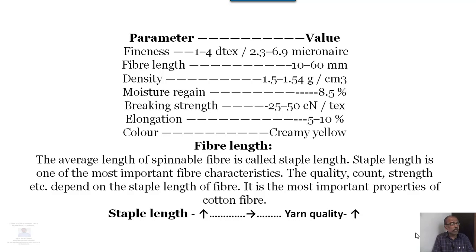Now, as the staple length is more, what is the consequence? Actually, the more the staple length, the better the yarn quality. Excellent yarn quality is going to be obtained, because when long fibers are there, these yarns can have an evenly distributed twist as they are required to be twisted. In unit number 1 we have seen this: parallel strands of fibers are twisted together to give strength.